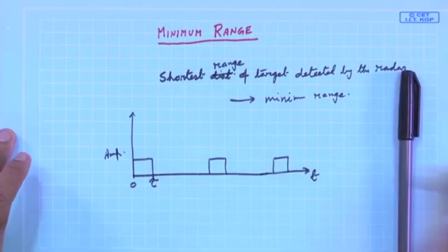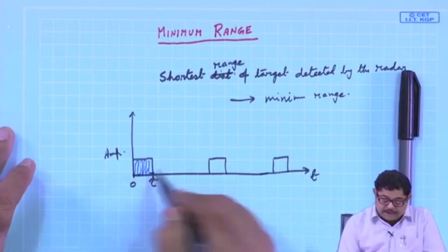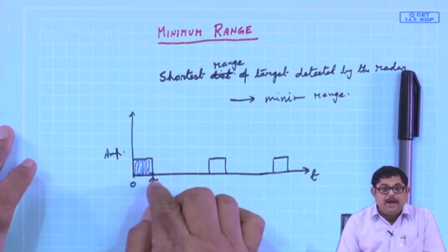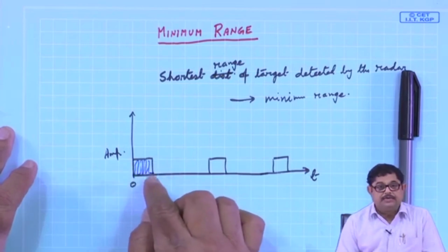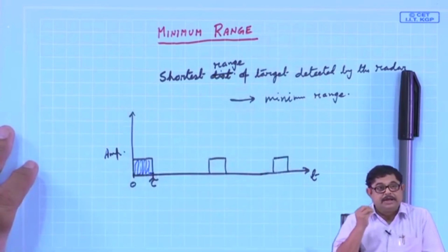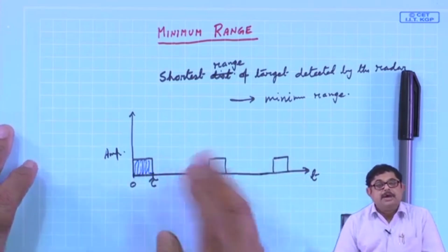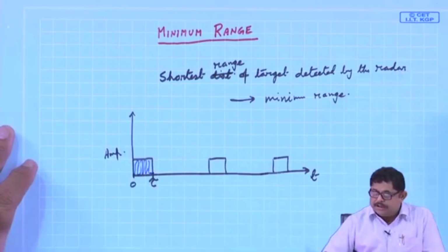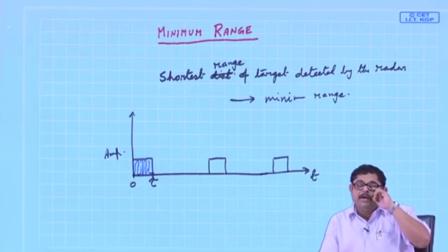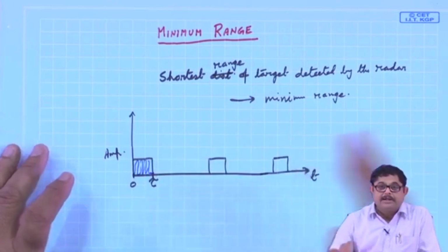The actual signal is a very high frequency RF signal in the gigahertz or UHF range. So, the signal is this, but if you take its amplitude, that is what we show like this. Please do not think that a pulse radar sends a bare pulse; it actually sends a high frequency carrier whose envelope may be like this. Also, the pulse is not always rectangular; we will see later that there are other shapes which perform better than the rectangular one, but to start with we are taking a rectangular pulse repeated at the PRF.